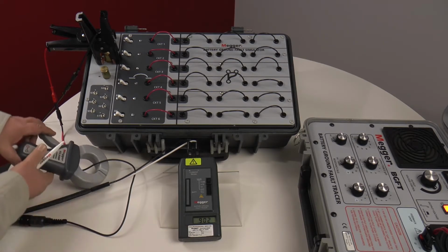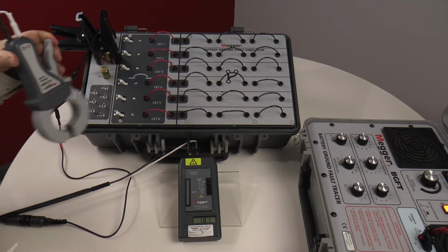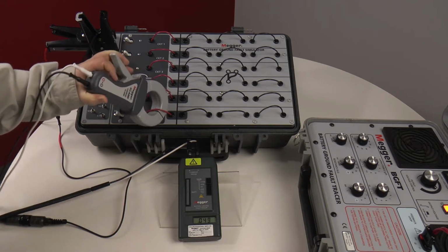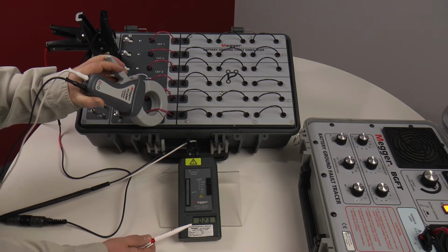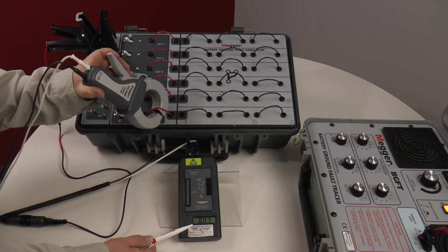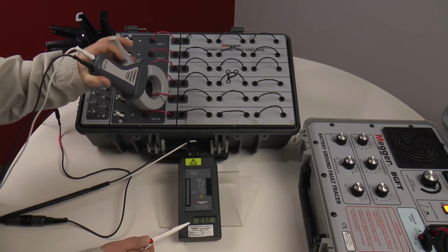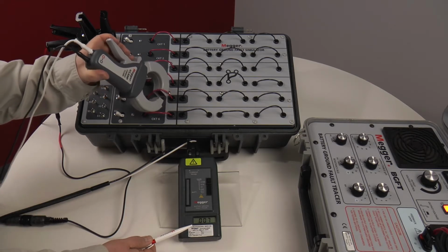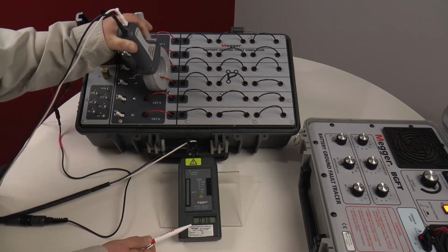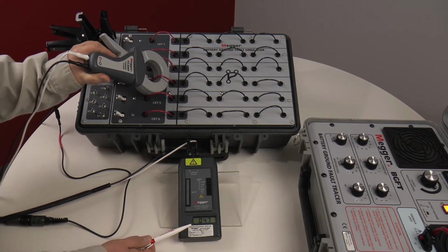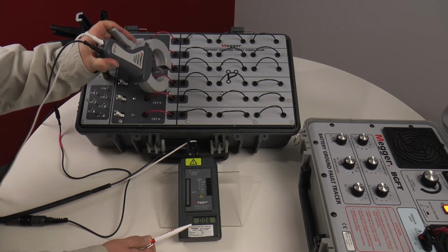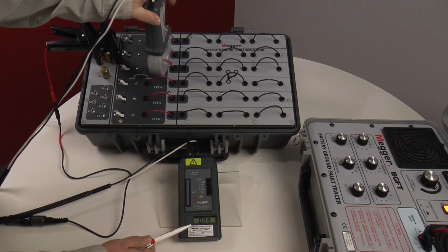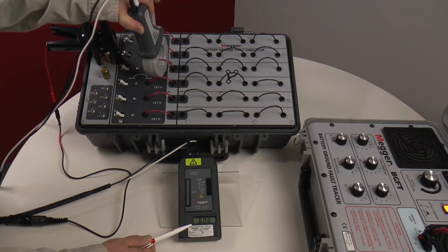In this case, we can see our total fault current was 0.902. So now we are going to start looking for that current. We start on circuit 6, and note there is no fault current on circuit 6. So we go to circuit 5, and we see there is no fault current on circuit 5. So now we go to circuit 4, and we see there is no fault current on circuit 4. Now we go to circuit 3. Here we see fault current, but it is not the total fault current.